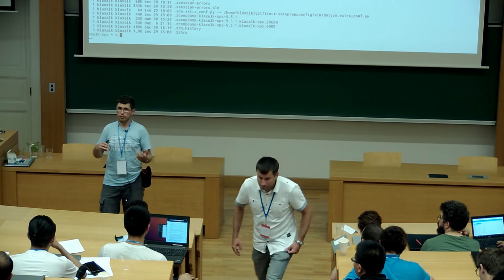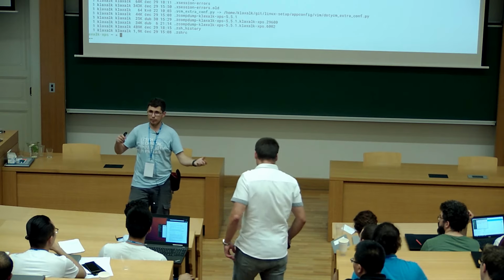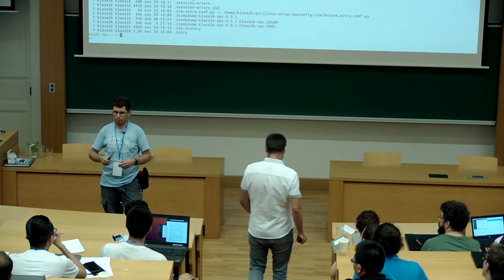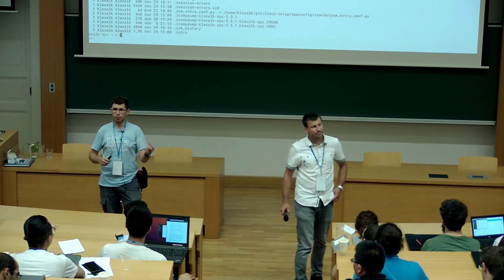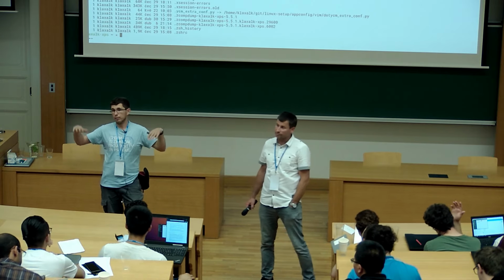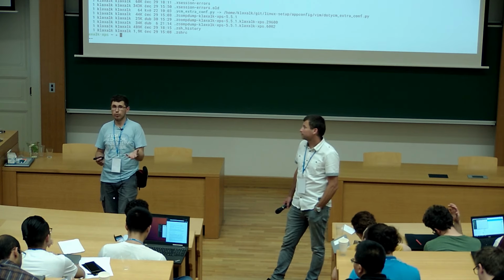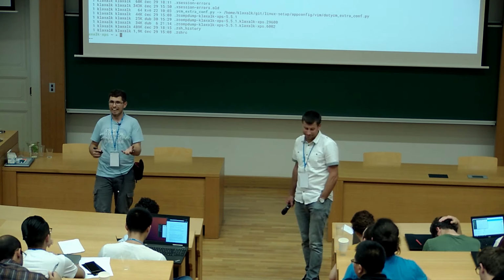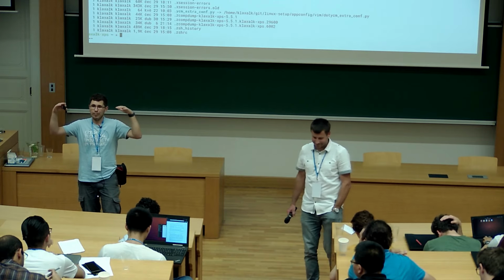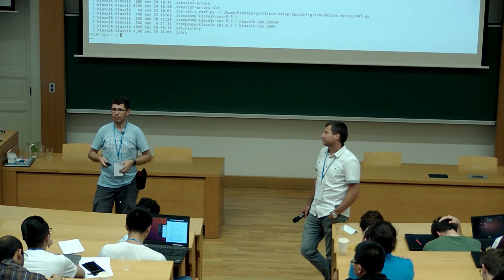We use a total ordering on the drones, so one drone has the highest priority and another the lowest, and when a drone detects a collision with other drones, they change their altitude levels based on the priorities. That's what we use currently. So it works only outside, because they can ascend really high to avoid collisions. This works only in open air.